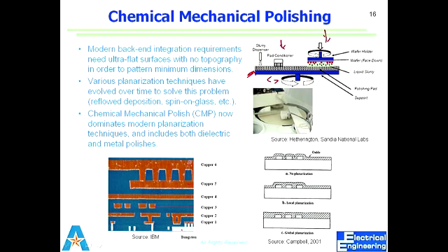I see. Why would you want to spin glass onto your electronic device, though? I mean, wouldn't that kind of cover up your contacts and everything? Yeah, we make the contact. Okay, so on one layer we have run all our lines horizontally, right? What we call interconnect. Now to get to the next level, we have to make these vertical connections, what we call vias. I see. So I've run my pipelines, and now I put my road on top of that, and wherever I need a connection underground, I make a vertical opening, which is what we call a via.